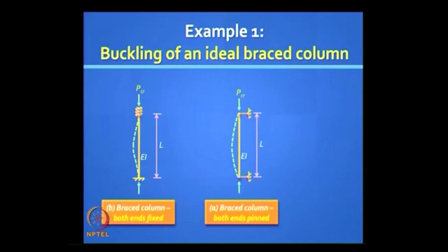Let us see if we can get this answer by matrix method. So obviously you need to create some nodes, right. How many elements would you recommend? This is just one element, you will not be able to get the result with one element, because the two ends have to, there has to be a lateral displacement, no. So you need a node, how many minimum?